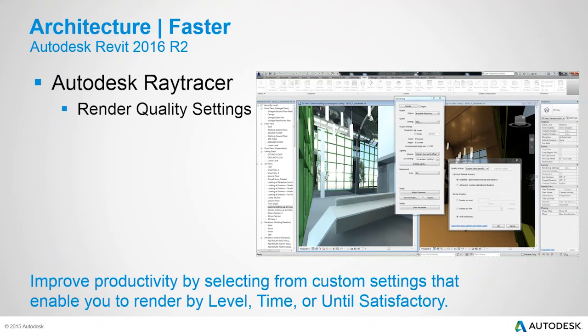In the Autodesk Revit 2016 R2, there is an enhancement to the Autodesk Ray Tracer that enables users to set different quality rendering settings. These are some new ones or improved ones. We can now select from custom settings that enable you to render by level, by time, or, here's a nice one, until satisfactory.